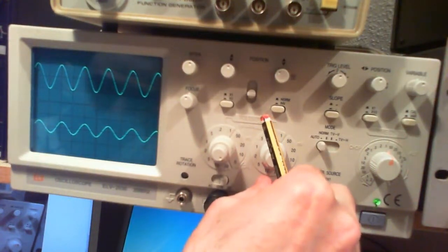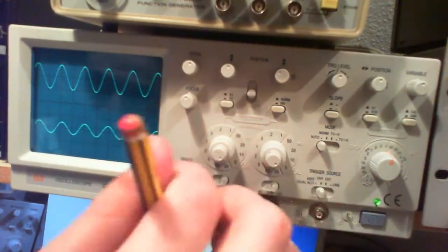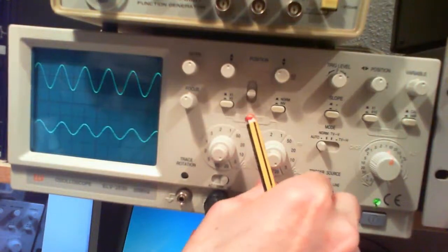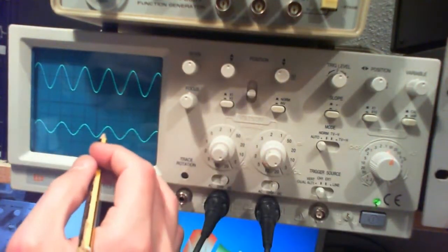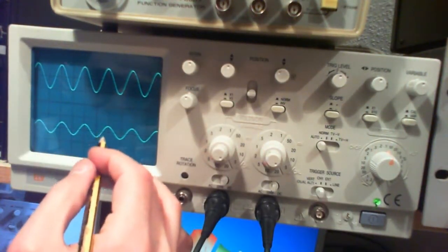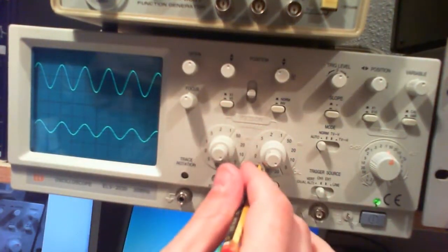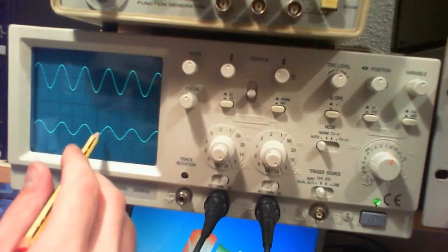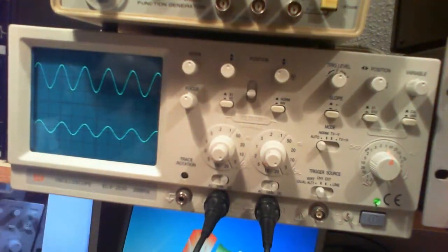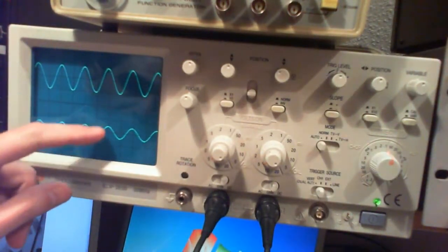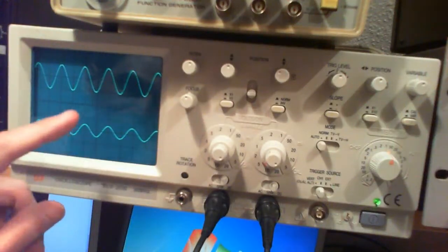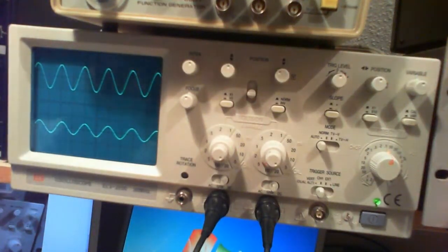But the ground that we have here is actually from this line over here all the way up to this line. That means that one division on channel 2 is 5 volts. That means that the amount of DC offset over here is only 5 volts, not 10 volts over here. Okay, so now